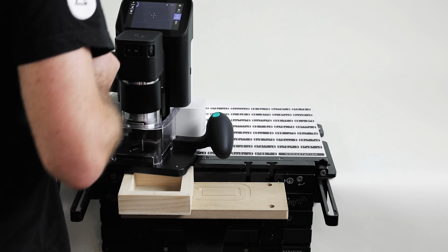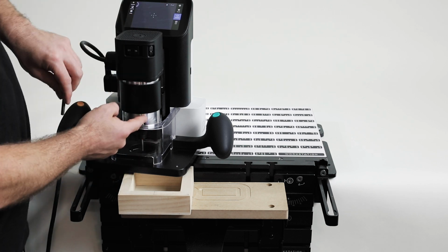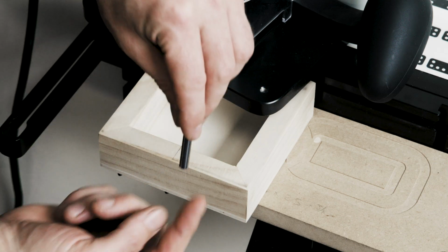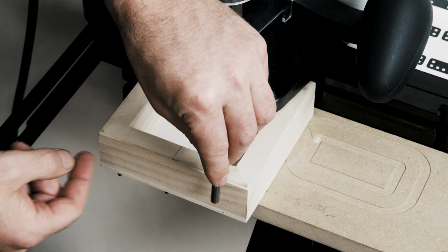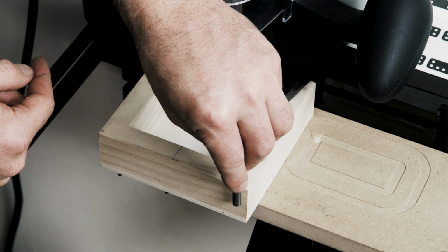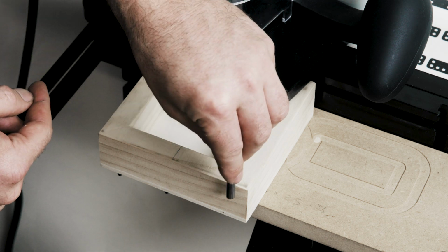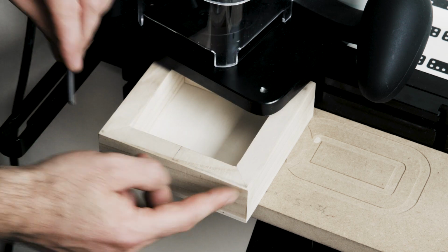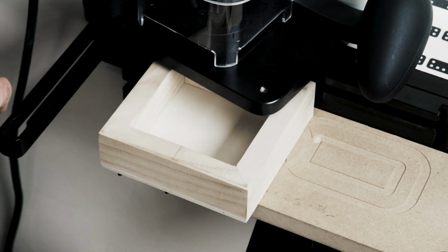To do that, we're going to take a cutter, insert it inside the spindle upside down, and use Origin's spindle mechanism and this perfectly round cylinder as a measuring device. We're going to drop it down below the surface and then bring it up and lightly touch it against the edge of this stock in two locations to get a straight line.